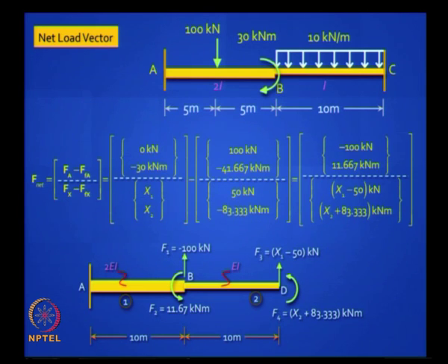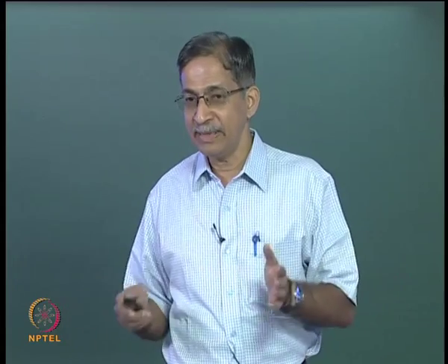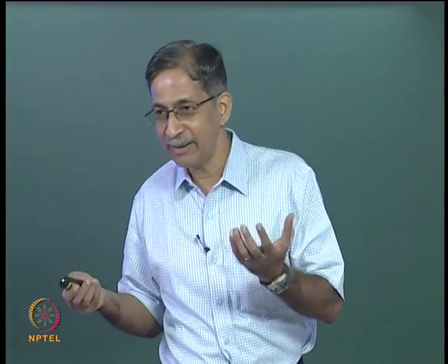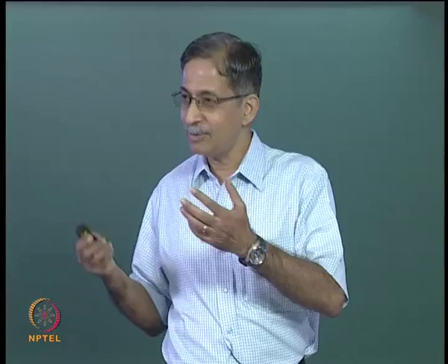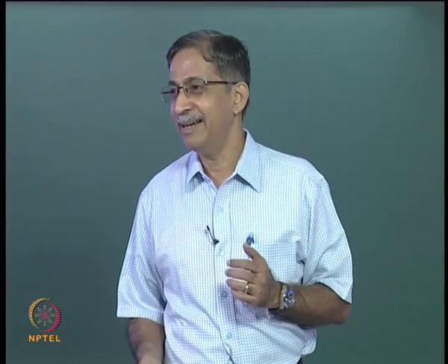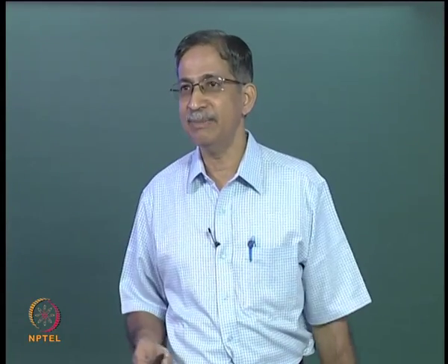So what is the next step? You have got the transformation matrix, you have got the fixed end forces, you have got the net loads, you are ready to solve the compatibility equation, but you need something. Before the structure you first need the element, and then you have to build. So we go to the flexibility matrix.